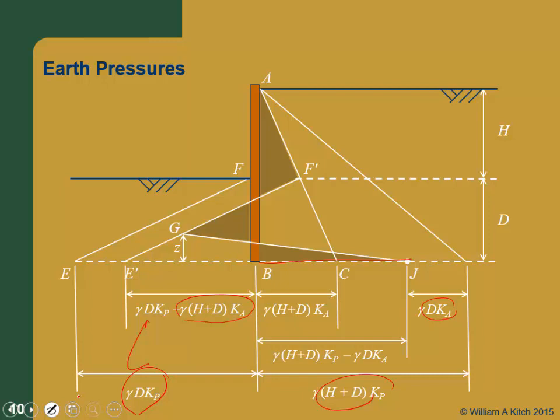The other one is if you're putting your factor of safety on the passive earth pressure. One way to think about that is that I'm not going to mobilize all of the passive for an ultimate failure mode. I've got the rest of that passive displacement to keep me from having a catastrophic failure. I may get large displacements, but at least I won't have an ultimate failure that way. But it's an implicit assumption in all these methods that we're mobilizing both the active and the passive together. And obviously the wall is rotating, so you can't have the same displacements everywhere.